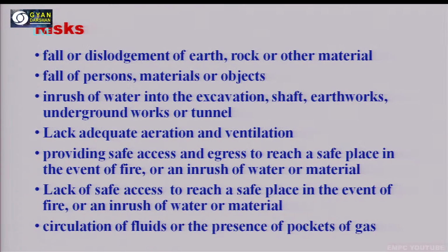Second, when you are working in deep cuts, there may be a fall of persons, meaning the workers may slip from a higher position and fall into those deeper cuts. There may be a fall of materials or other objects. When these materials and other objects fall on the workers who are working deep inside the cuts, they may harm them and cause injury to them.